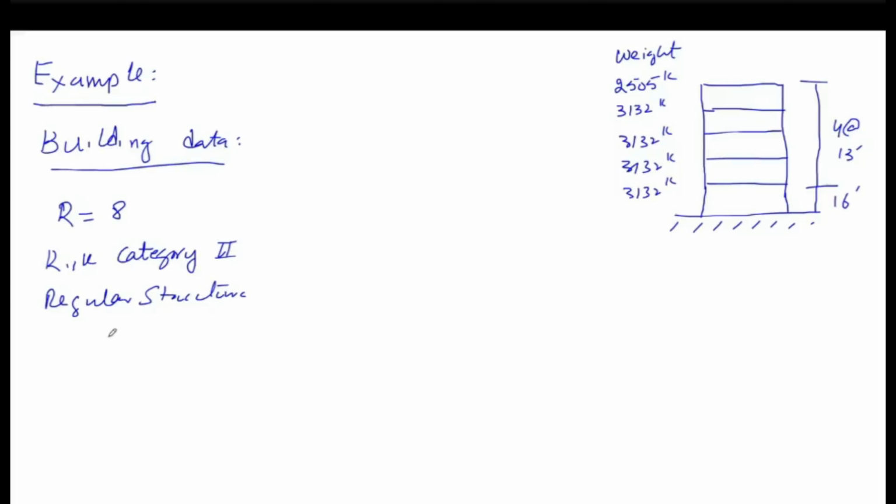The site latitude and longitude are given. This is obtained from one of the examples from the United States. If you know the site latitude and longitude, you can obtain the geotechnical data for the design. The site latitude is 35.29607, and the site longitude is minus 120.65306.